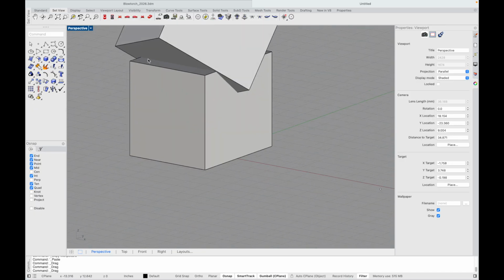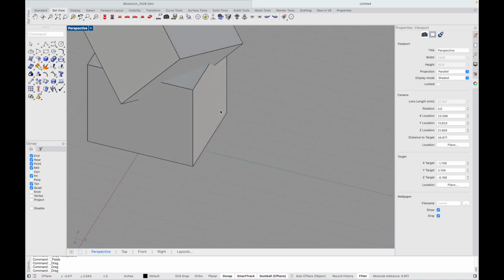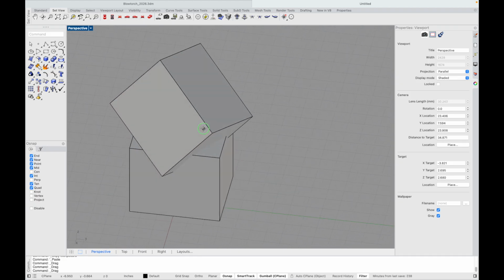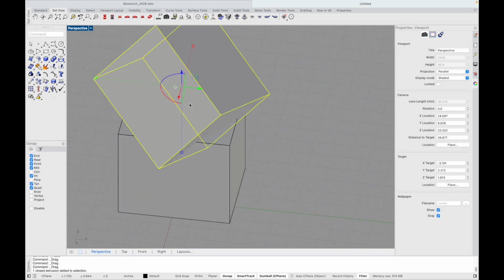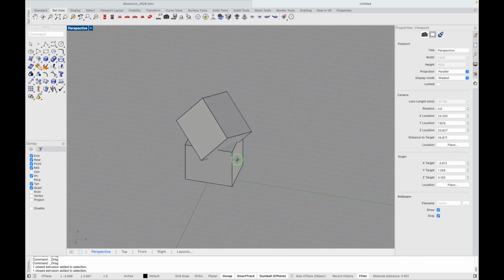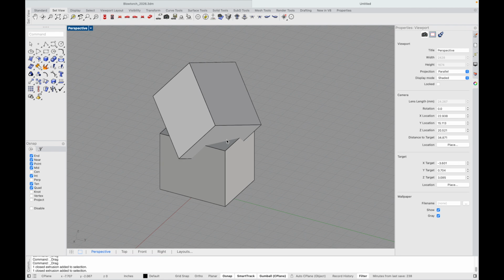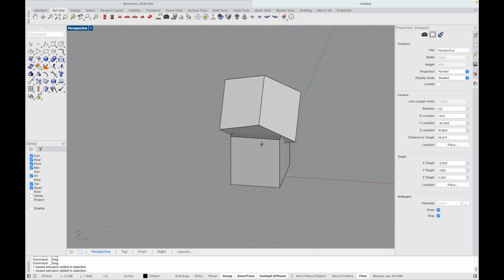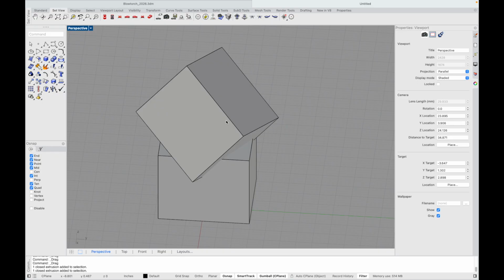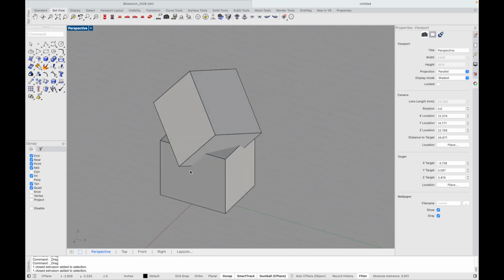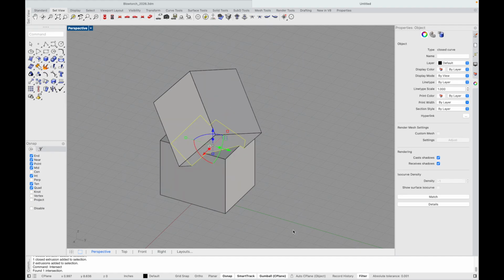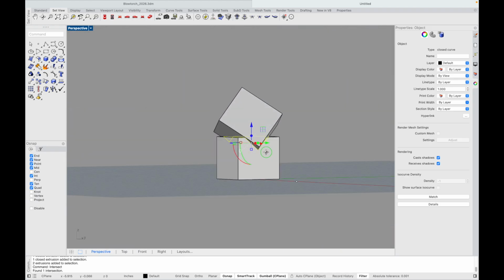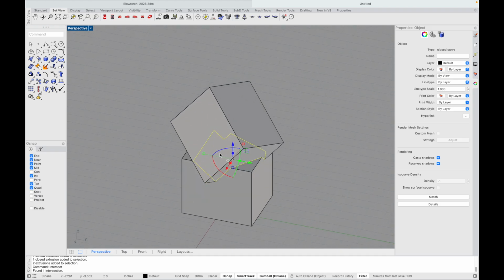So what if I wanted to figure out what that curve looked like where these things are all smashed together? Well, this is a great place for that intersect command, because remember, there's no actual curve there. These boxes are just crashing into each other in space. So if I wanted to create something from this boundary, or subtract this front box from the other box, then the intersect command would give me a visualization of what that boundary looked like. So intersect, cool. You can see that just created a curve where these things intersect, right?